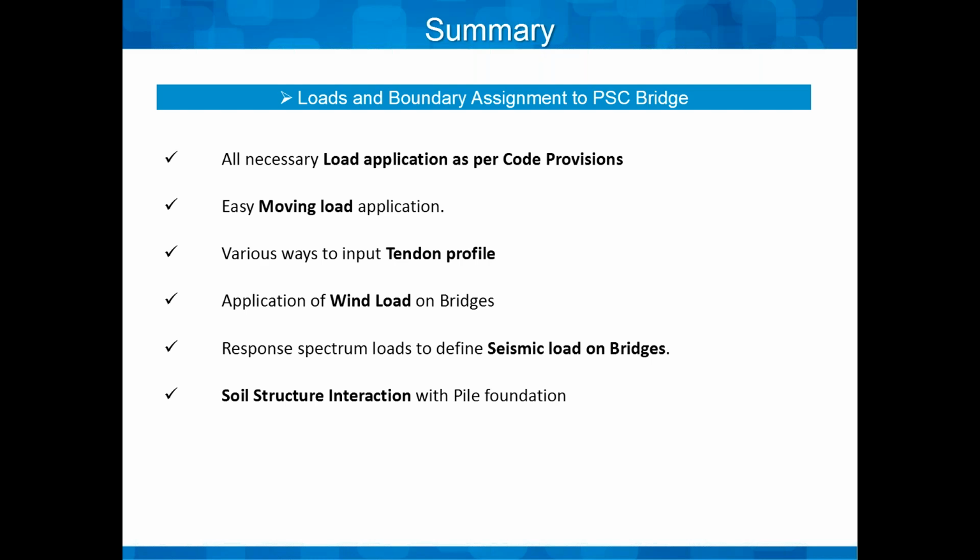Apart from that, there is optimization too. Another part we saw today was about tendon profile, which was very easy to apply for different girders, and how various ways are available for us to define them. Then the application of wind load on bridges was very easily done by simply calculating the forces and applying using the element beam loads.